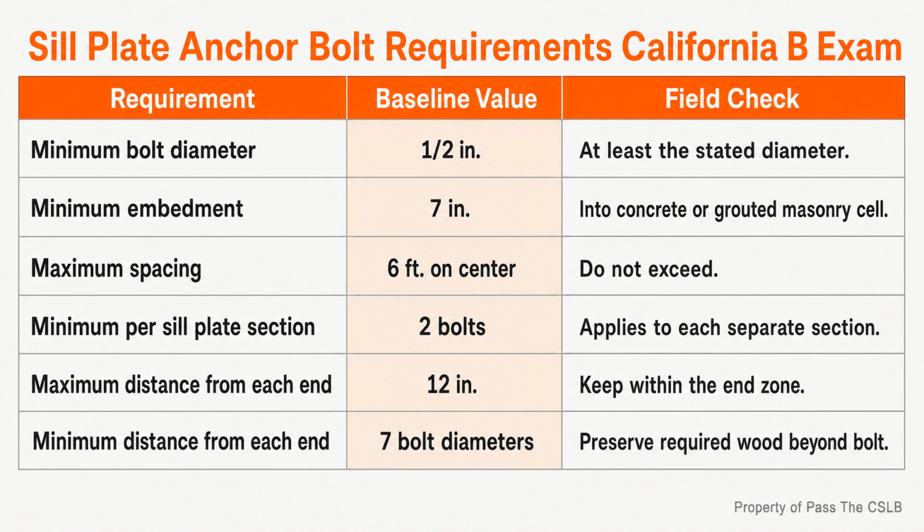This is where sequencing protects the schedule. Catching a misplaced wet set bolt while layout and concrete work are still open gives the project more options. Discovering it after drilling the sill, standing the wall, installing finishes, and covering the connection turns a small layout error into demolition, engineering review, and delay. I treat anchor layout as part of the structural path, not as a concrete detail that belongs to someone else.